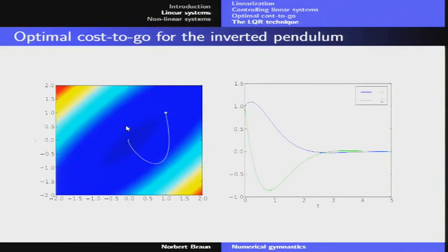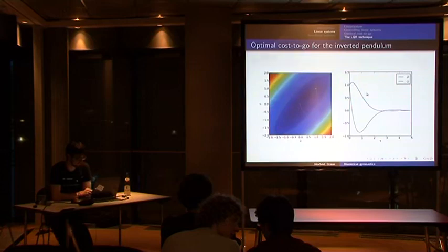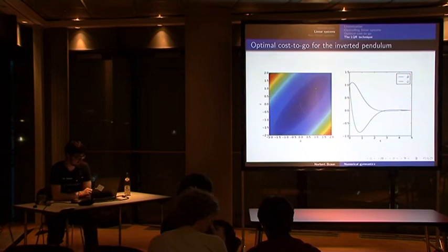And if you look at this over time, here's time, and again we got the distances in position and in angular velocity. You show that it nicely takes you from a rather large deviation to the goal. Remember that 0 corresponds to the pendulum pointing upwards. This really works. Now, of course, this is not particularly interesting. It wouldn't really make sense to introduce this framework if this was the only kind of problem we can solve, because a PD regulator can do this just as well. What's more interesting is that it also works for underactuated systems, such as the Acrobot.